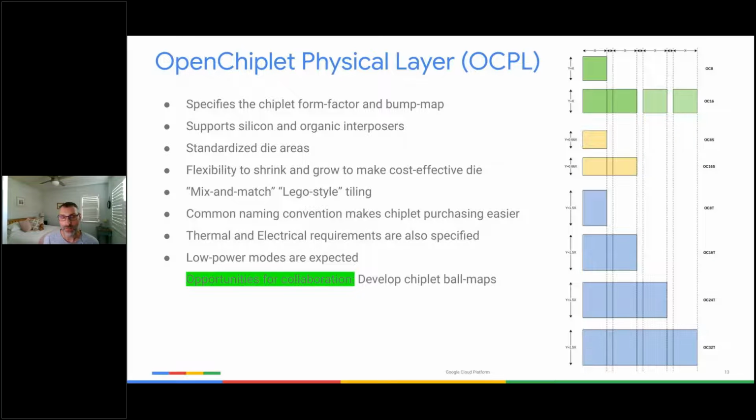A post-assembly test, and the ability to run as much test coverage as you can on that silicon die, maybe through functional test or logic BIST, and you've also got to check the end-to-end connectivity. But like I said, it's an interesting question that came up certainly when I was doing the panel session as well.